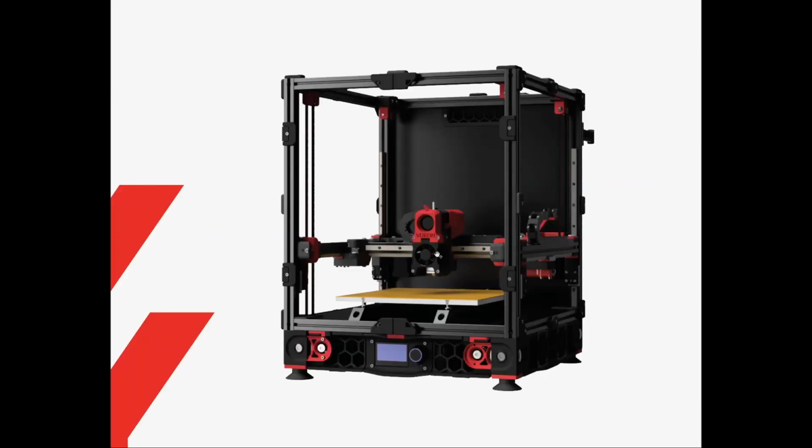By the way, I forgot to tell you, the same applies while you are running the AB belts, same method as with the Z belt. But in here, don't make it flush. So leave 2 centimeters or so in here at the beginning of your belt, and screw the cap and run your belts, and again tension with your hand a bit, and again leave 2-3 centimeters, and count your remaining excess teeth, and apply the same thing for the other belt.